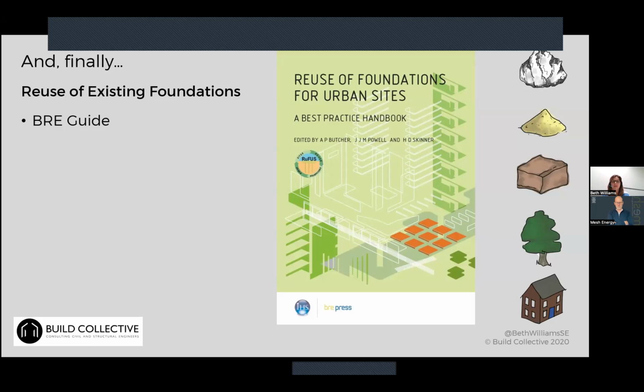If you're reusing foundations that were designed for a certain loading arrangement and loading type, you would want to keep the loading from your new superstructure very similar to the loading profile of the original building. The main thing is that you don't want to introduce significant point loads into your foundations where there weren't point loads in the first place.